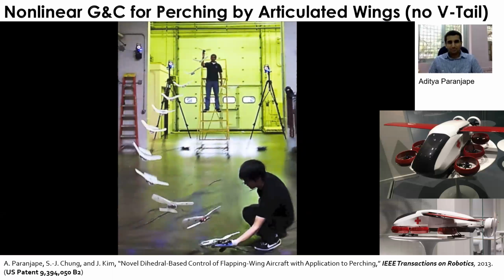So this is our flight task where we validated our nonlinear flight controller that can enable safe transition from the vertical takeoff and also even vertical landing to forward flight using fixed wing. So having this kind of stable transition is the holy grail of this VTOL with a fixed wing.